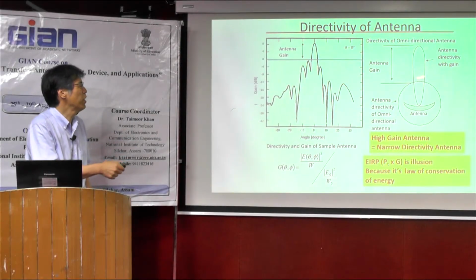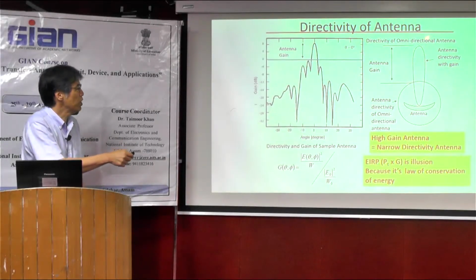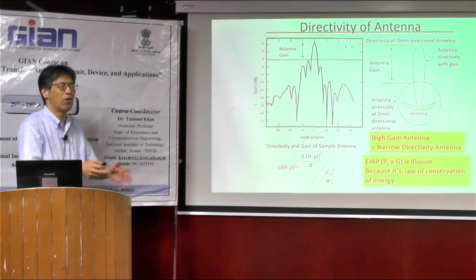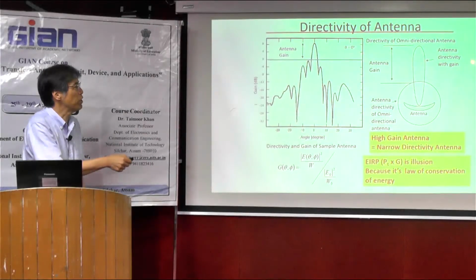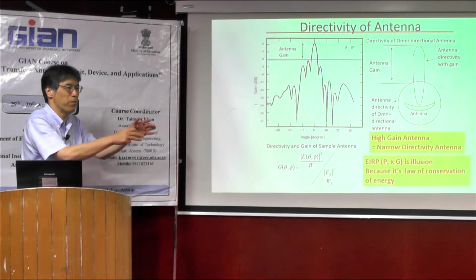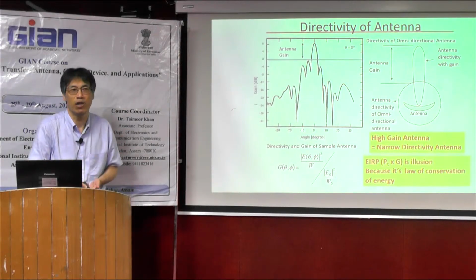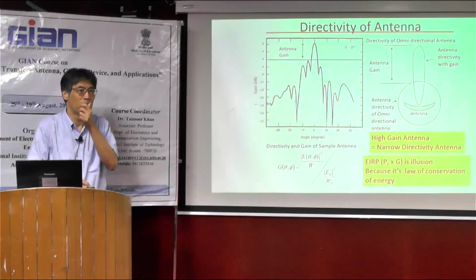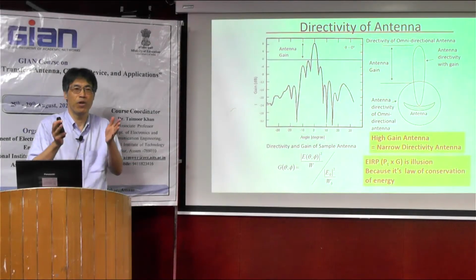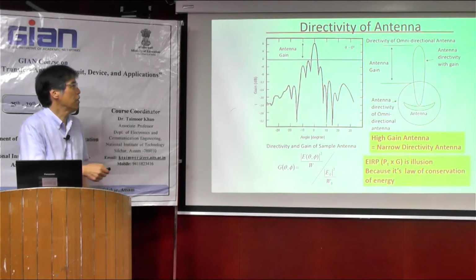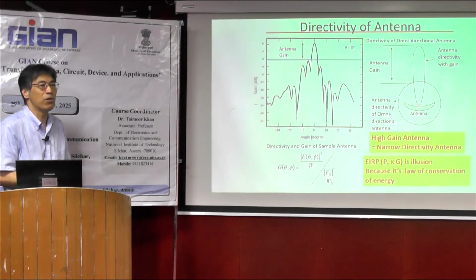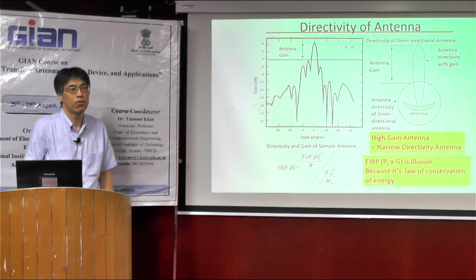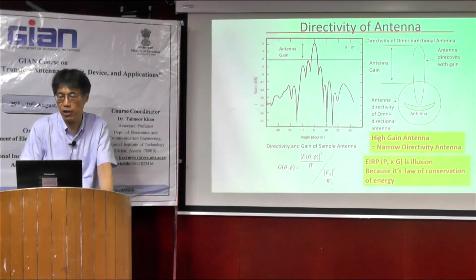But if we have a high gain antenna, in this case, from the front wave, we can gather enough power. But when a source is away from the front gain, unfortunately, gain becomes very small, and we cannot gather enough power. So it involves pros and cons. High gain is very good because it's a very large aperture. But suddenly, it becomes a very narrow directivity antenna, and sometimes it's not suitable for the energy harvester. So we have to consider these pros and cons to develop the large antenna for the energy harvester.